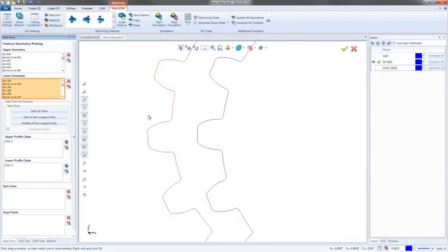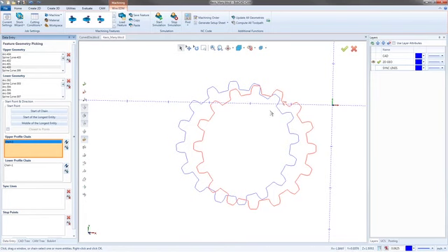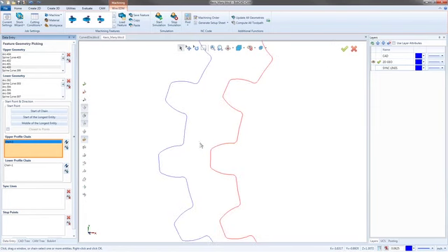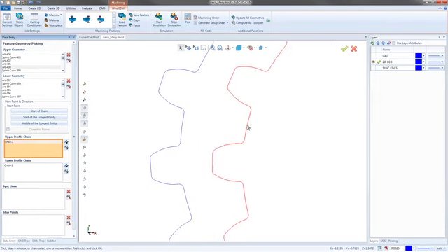I want to be as close as possible when I'm picking my geometry, because a lot of times there's the start point. It doesn't even pick the start point. I was shooting for it, but it didn't do what I wanted it to. So I'm just going to move the start point over there anyway. And then right here, I'm going to go to the lower chain profile and just do the same thing. I want them both sitting right in the middle. So we should now have both start points. We want them close to each other.